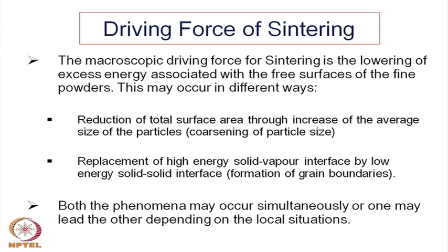or strongly bonded at the green condition before firing. We have said earlier that normally the powders are consolidated by applying pressure or by some casting techniques. So, if that is not done, just the loose powders getting heated together, there may be particle coarsening, but no mechanical strength really gets developed. So, that is one way by which the surface energy term can be reduced.